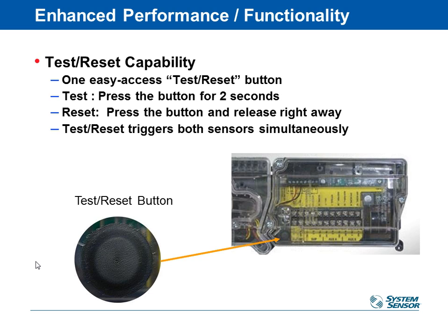It's kind of like a freeze stat. No one wants an auto reset freeze stat because then you don't know that you're about to freeze pipes all the time. You want it to be a manual reset so somebody has to walk up there and see what the heck happened. Same thing on smoke detection. It's a manual reset. After it trips, you need to go up there and reset it after you fix whatever the problem was. Hopefully there was not a real fire.